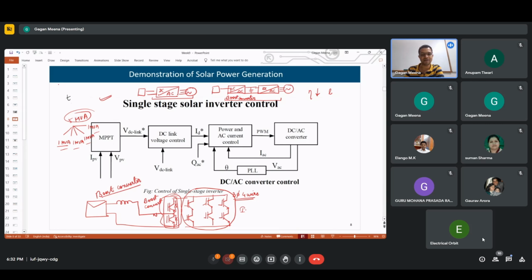Then this is bi-directional controlled. So in this we have vehicle to grid. The vehicle can supply power to the grid. For this we need an aggregator in between. One vehicle cannot provide a sufficient amount of power to have any impact on the grid, or the grid cannot provide grid support services alone. So in between we need an aggregator which can pool different electric vehicles to provide those grid support services.